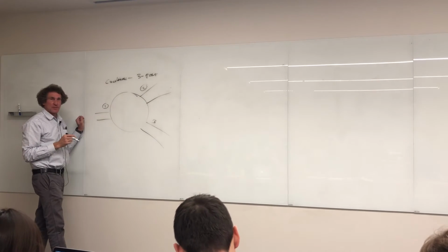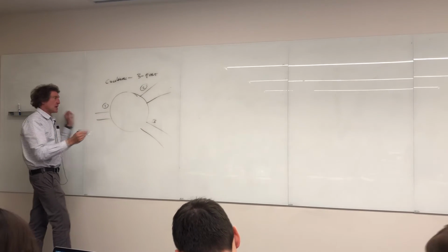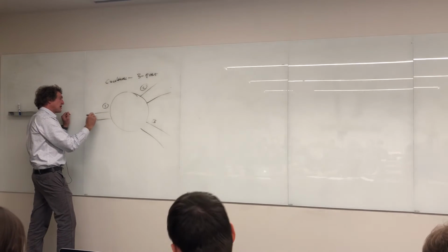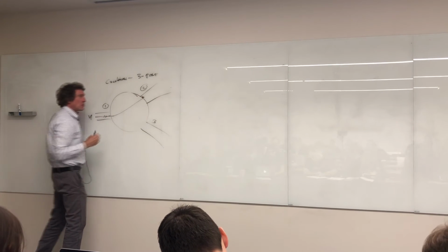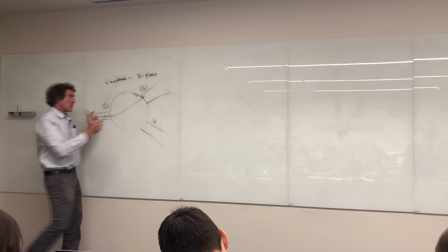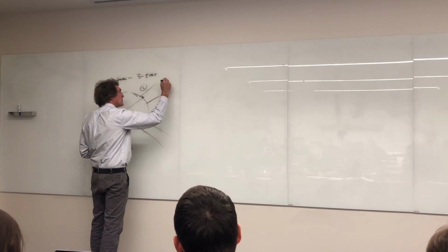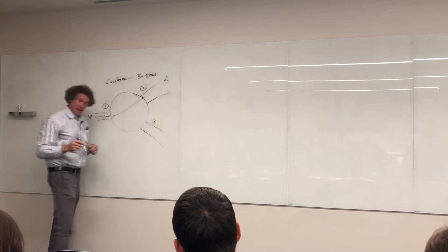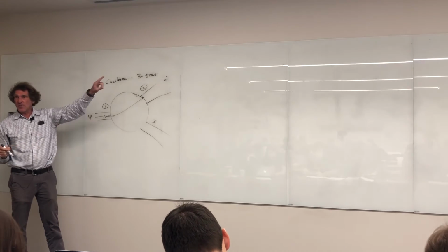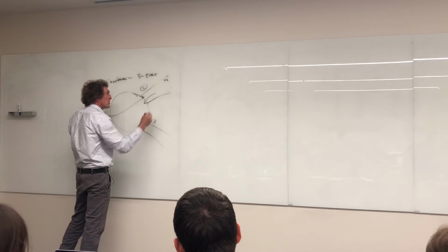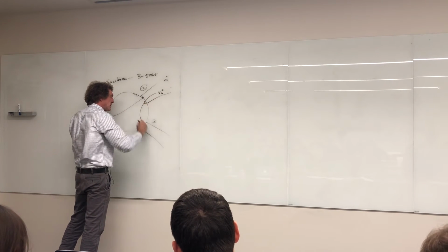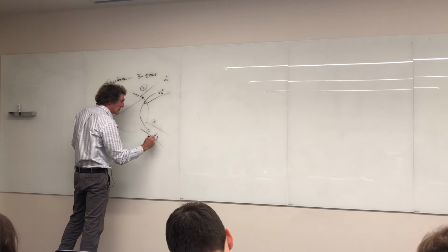Now here's the goal of a typical circulator. If this is V1 and you have V1 plus coming in, they want all that signal to come out port 2. So they want all this to come out V2 minus. Then they want all the signal incoming at port 2, that would be V2 plus, to come out port 3, that would be V3 minus.